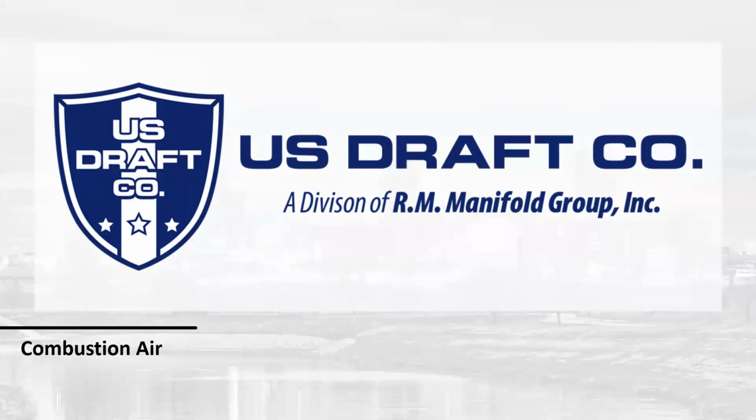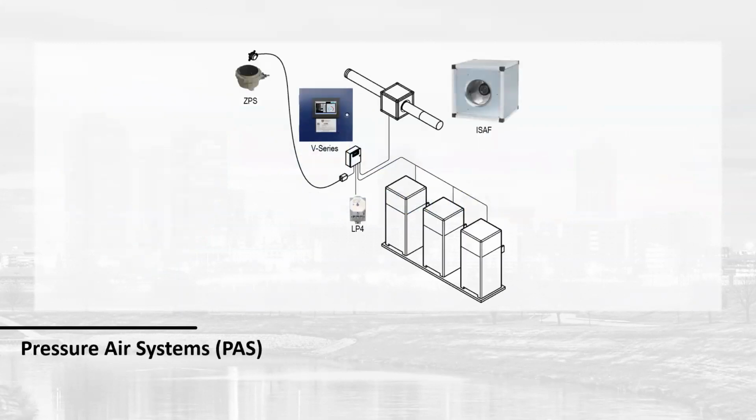Combustion air, the final piece of the puzzle, is how do you get air into the space? There's a few different ways. You can obviously put big louvers in the wall, or you can put pipes going to the boiler. We have offered what we call our pressure air system. So instead of having a big louver in the wall, or instead of having a big duct running to drop down to each boiler, we'll just have a single pipe dump it into the space. We'll have an inline fan, controller, outdoor sensor, and pressure sensor in the room. And all we're going to do is modulate that fan to maintain neutral in the space.